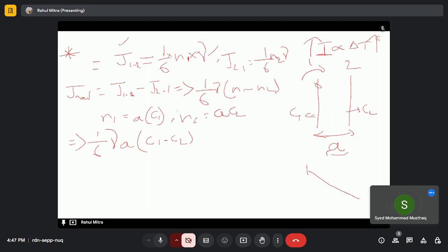And what happens if we have a G versus X plot? What happens now? If we have an alloy composition here and we give enough temperature, then this alloy will decrease its Gibbs free energy. And here we have an uphill potential where the atoms are getting richer and richer in one phase. So for conventional purposes, we are using that diffusion only depends upon the concentration gradient.